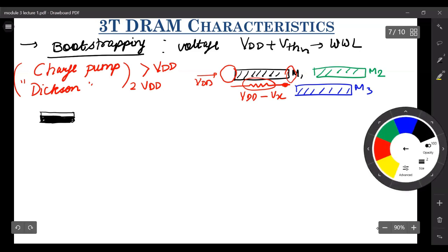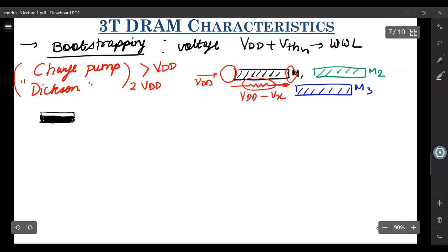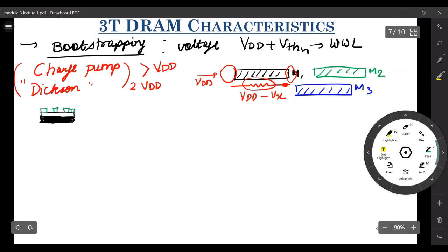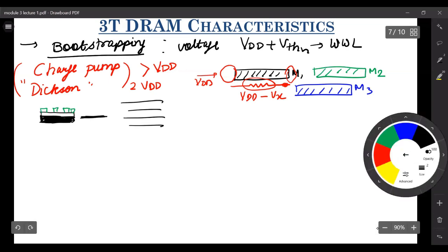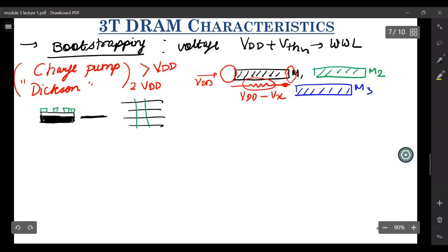And then you have your metal 2. Now your metal 2 goes in a different direction. Let me tell you how. If you are routing M1 in the horizontal direction, like if you look from the top, if you are routing M1 like this, your M2 will be routed like this, perpendicular to it. So in this side view, if you have M1 going in this direction, you will have M2 coming out of the page or going into the page, something like this.